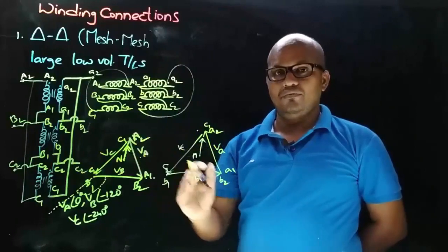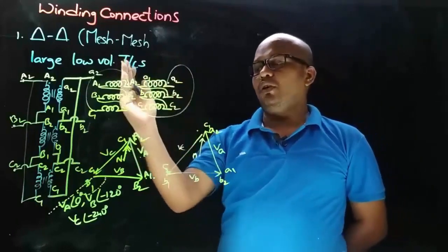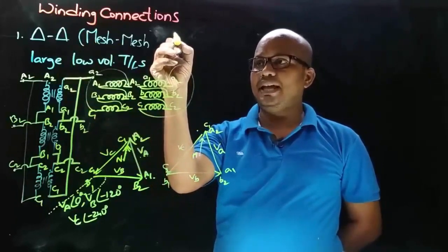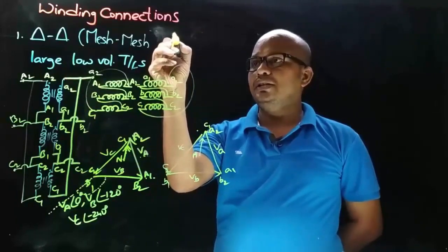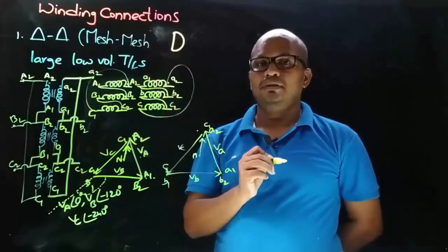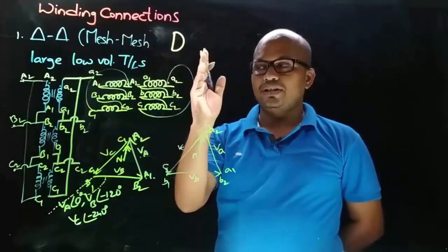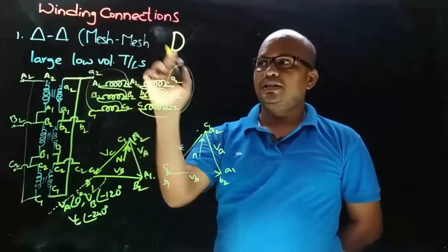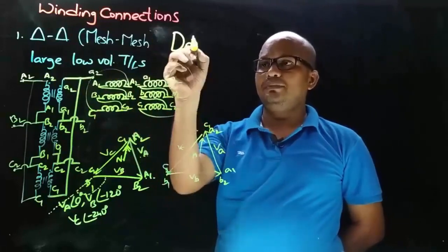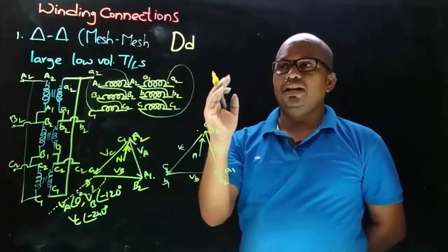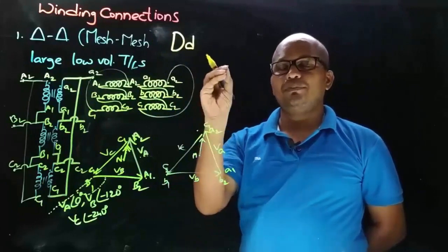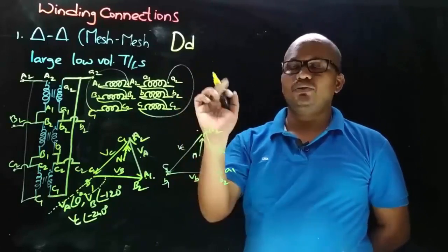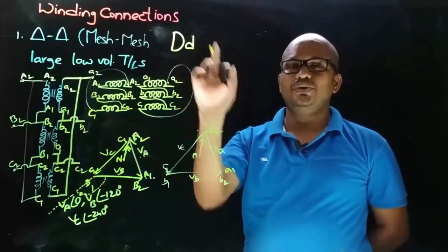So with these phasor diagrams of delta-delta connection, first let's observe the vector group. Here on primary side the connection is delta, which is represented with capital letter, so it is capital D, and the second letter is lower case, and here the secondary is also delta connected, so that will be small d. And the third is a numerical which will represent the LV side phase displacement with respect to primary side. So now let's decide the third position numerical.